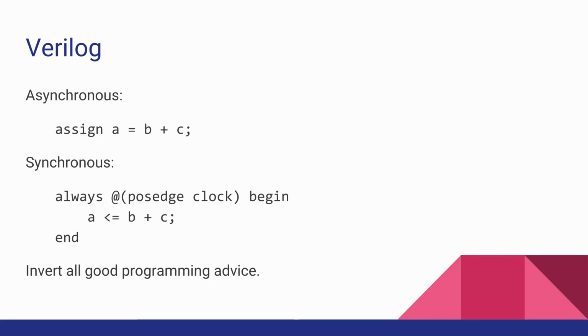So instead, you want this code, which looks similar. It's got a different assignment operator here, but it's the same thing. This part, B plus C, is exactly the same as on top. It does the exact same stuff. Takes B, takes C, routes them together into an adder, and the output is anonymous. It's not named, and just sits there. And then there's a separate thing called A, which is like an 8-bit flip-flop, sitting there, but because the flip-flop doesn't accept the data till you hit it with a clock, at the positive edge of the clock, those anonymous signals are actually latched into A.